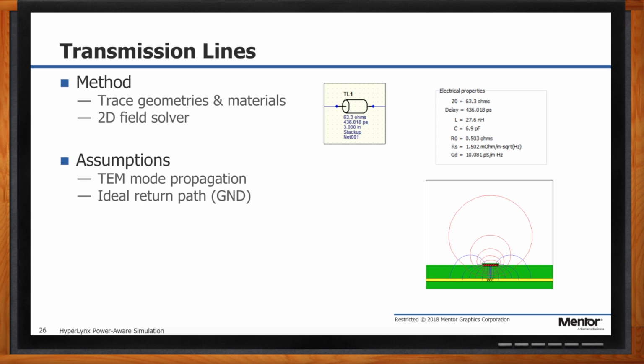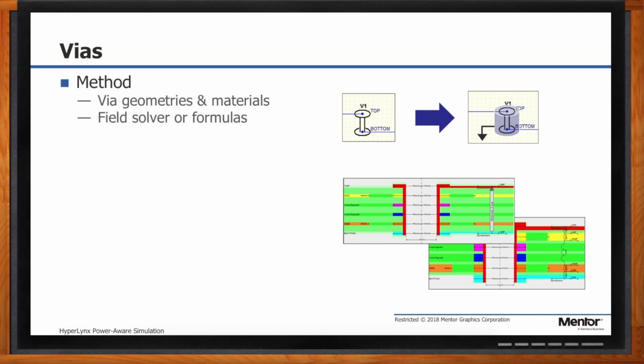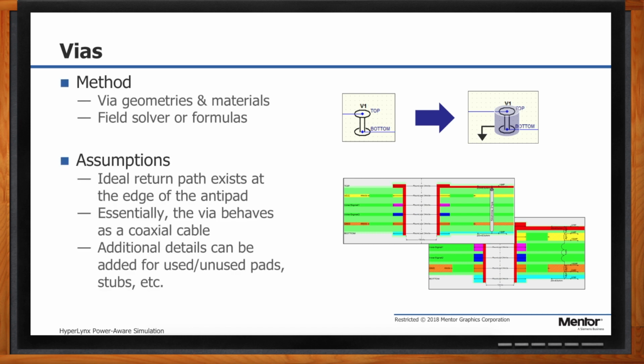If we look at the via models, they're interesting. I've been doing this for 20 years, and I didn't really internalize a lot of the idealized assumptions that are made with most via models until I actually started preparing the material for this webinar and this particular release. And so what will happen a lot of times is we have a via model. We know that's a cylindrical structure through the center of the board, and we'll look at the via barrel and we'll look at the antipad and the planes beyond it. But when you really dig into it, and really every signal integrity tool makes this same assumption at base, they look at it and go, okay, we're going to treat this as a coaxial cable. We've got the center conductor, and then at the edge of the antipad, we've got the planes, and we're going to pretend that there's just metal going from plane to plane there so that we have a perfect coaxial cable. Except for the fact that you don't.